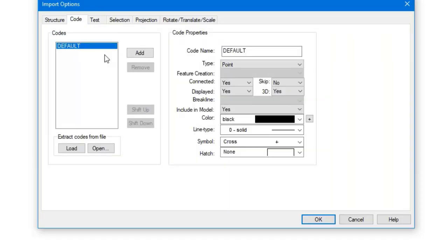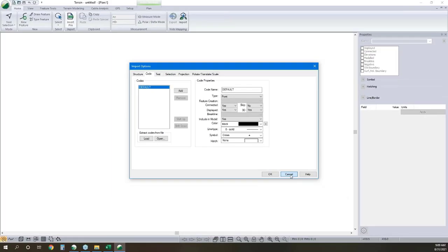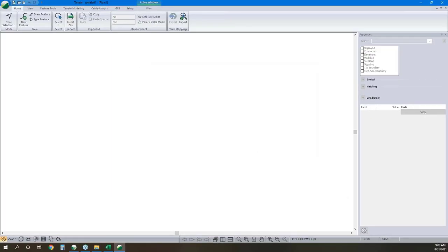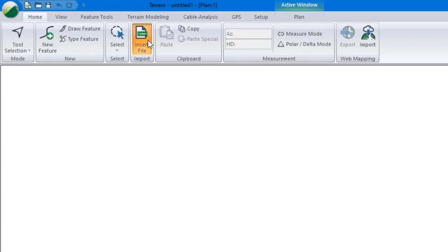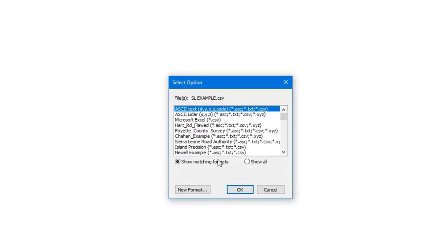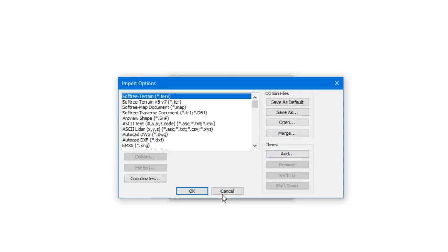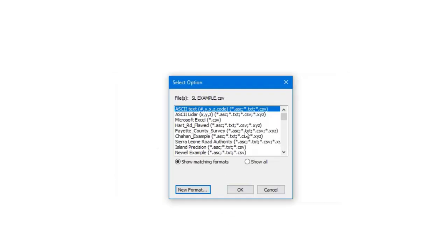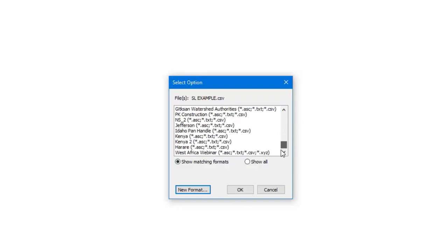And then I could come over here and start defining my codes. Now you'd only have to do that once. After you did that, we could hit save as default, and that would be configured on startup. Now, I've done something a little different here. So I've gone through and I clicked new format previously. I've clicked add, and I made one of these IOP options. So our software system settings are set up so we can match the survey standards that were followed and really streamline the process.